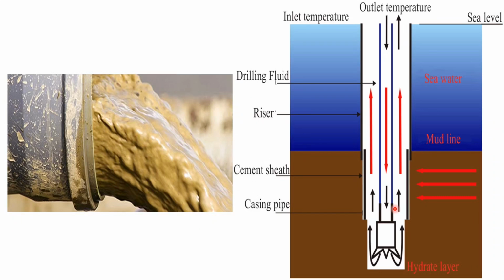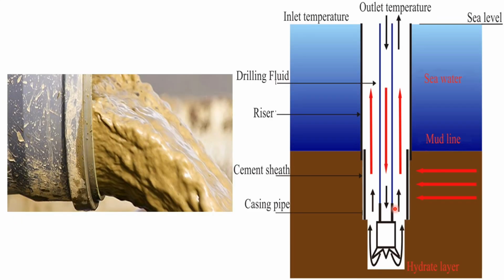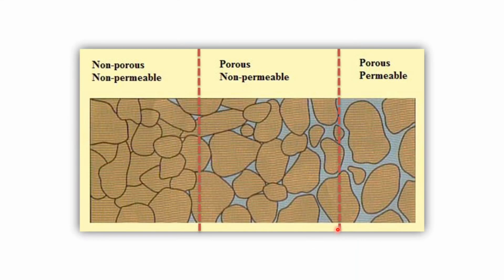And the other parameter that can be found by logging is the moisture content. The moisture content is the percentage of the moisture in the unsaturated zone, and this is an important hydrologic factor that is related to the evapotranspiration and also the recharge, because based on the moisture content we can understand whether the well is being recharged or not.